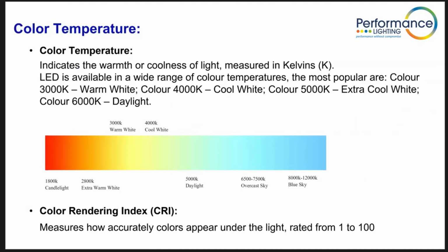Strangely, and we won't talk about it too much today, the human eye is an amazing thing. It can see millions of colours, it can see colour temperature, but it can also trick you. If I set up two rooms at exactly the same lux level, which is a measurement of light, say both 500 lux, but at two different colour temperatures, one warm white and one daylight, and I asked you to walk into both rooms, you would say the one in daylight was definitely brighter.